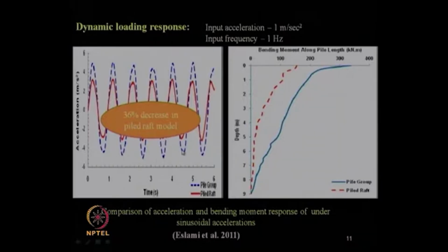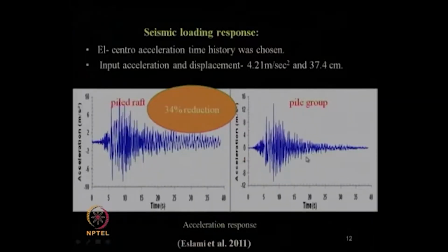So, which is beneficial of course. As well as you can see from the results of Eslami et al. 2011, it shows a 54% decrease in the pile raft model in the amount of bending moment along the pile length.